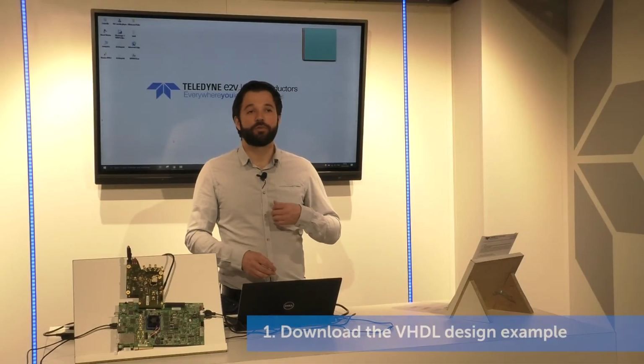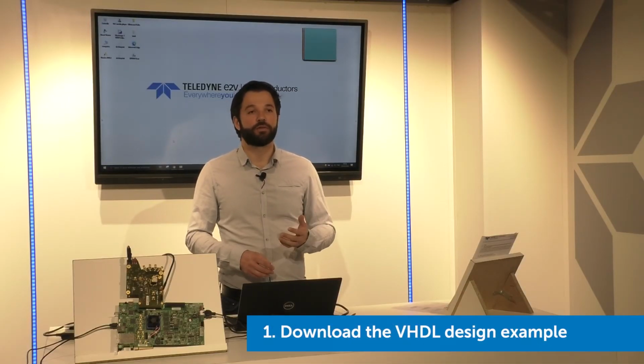First, download the package for the KCU105. The package contains all VHDL and constraint files, a graphical script to generate the project, and a Python script to create a graphical user interface.